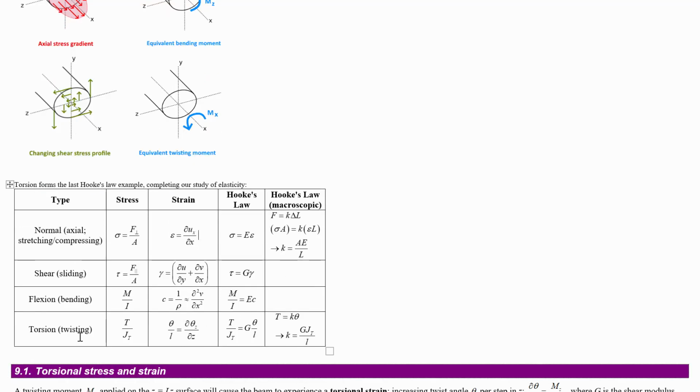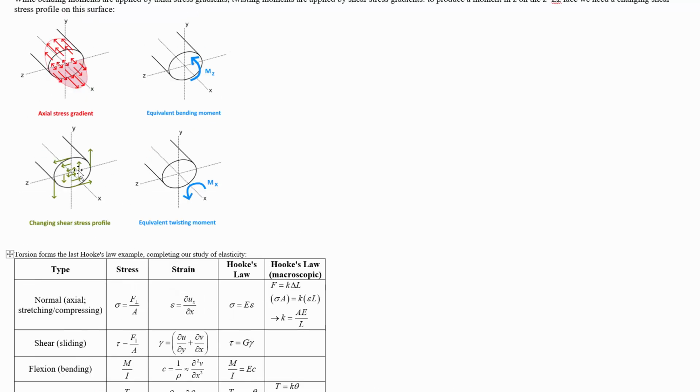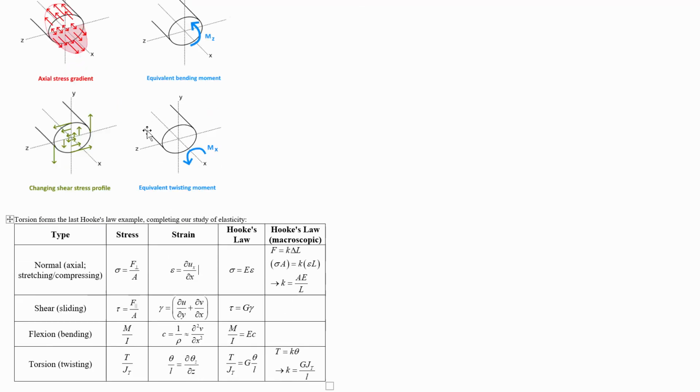This week, we're going to see twisting deformations, which are torques divided by torsion modulus, related to the second moment of area in bending. And that thing is going to be related via the shear modulus, because again, this is like a shear phenomenon, twisting, unlike bending, which is a normal stress or axial stress gradient phenomenon.